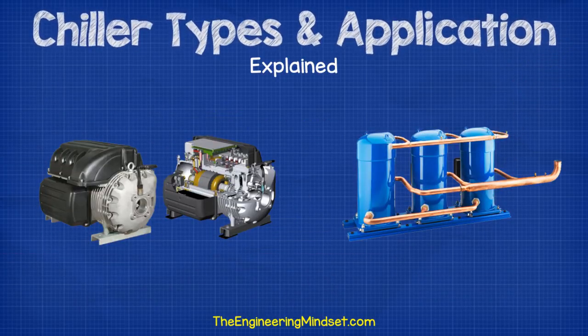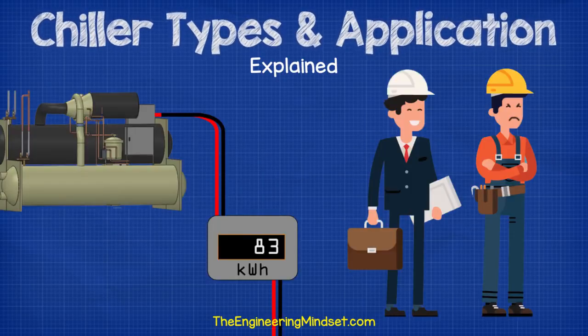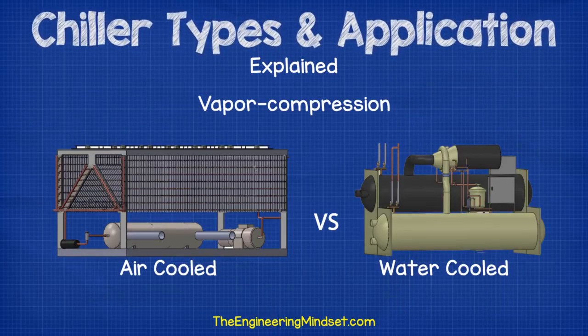You might need to use chillers with multiple compressors that can work independently from one another, so that if one compressor fails, then the chiller can still remain partly operational. Unfortunately, many building owners want the cheapest upfront option, but this is a bad idea because for a little extra, they could have bought a more efficient chiller which would be cheaper to operate, especially as chillers last around 15 to maybe 25 plus years in operation, so it would have paid for itself multiple times and would have resulted in reduced environmental emissions. So how do you decide between choosing an air-cooled or water-cooled chiller?